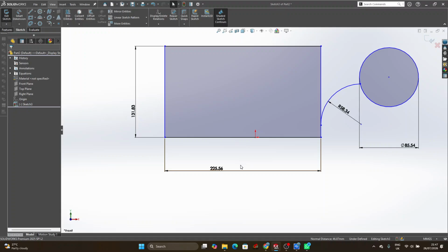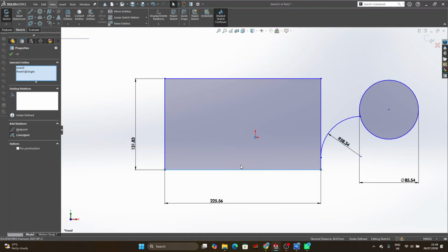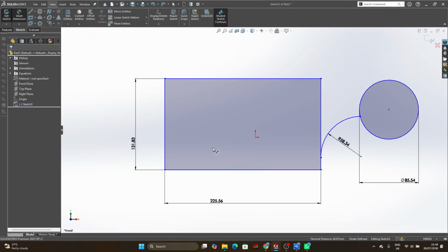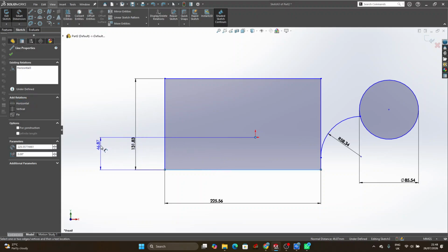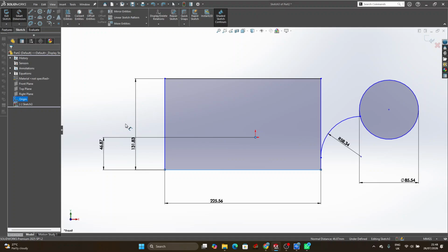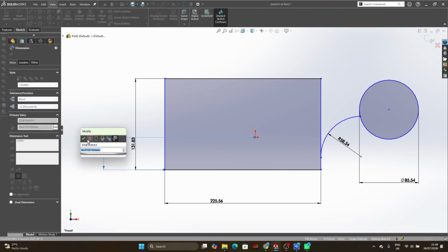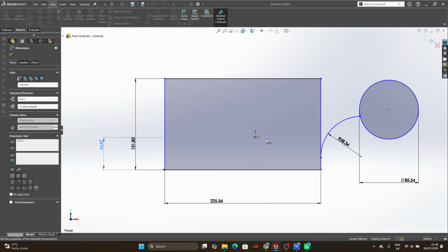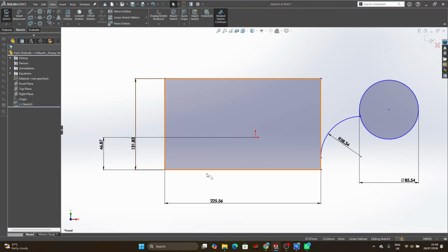Or another option, I can use dimension without using these two. I can just press Ctrl Z to go back and click on the dimension once again and click on it like this. Do you notice what I did now? It's already dark around this side too. Can you notice this side is already dark? Which means along this area, I've fully defined it along this side.